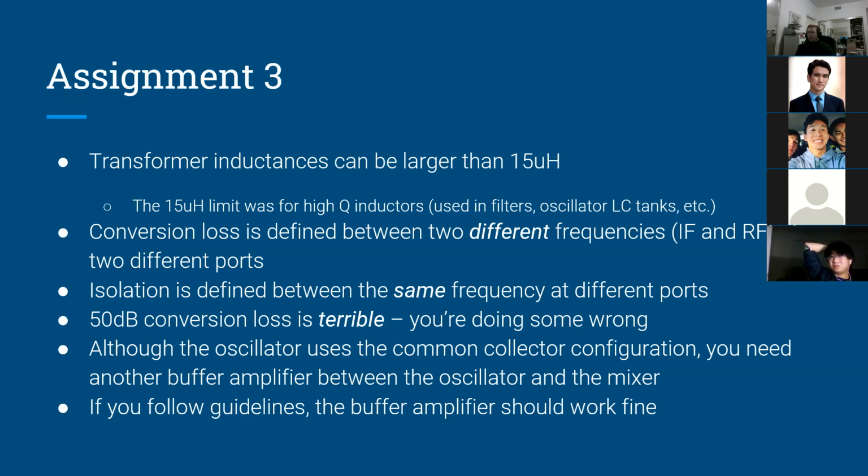So there's a thing called load pulling, where if you have an oscillator and you attach a load to it, that load, depending on its exact magnitude and phase, will cause the frequency of oscillation to shift as well as the amplitude of oscillation, even if you have a common collector amplifier as part of your oscillator.